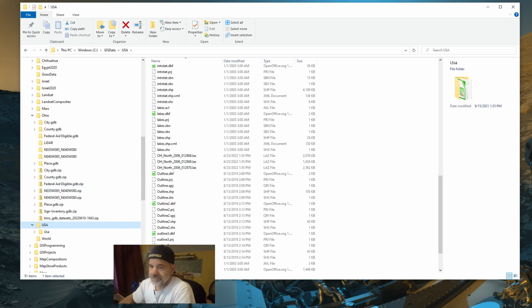Now what? Okay, let me tell you about LAZ files. ArcGIS Pro cannot directly read a LAZ file. It has to be a LAS file. I know that that's confusing.